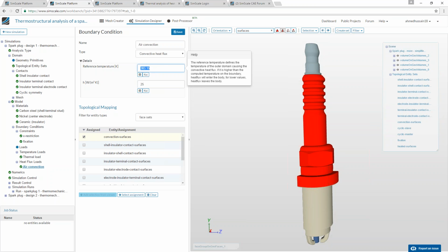Okay, there is another question from Joseph. He said, in the meshing phase, do you have to have a conformal mesh, meaning node-to-node connectivity between nodes across different material blocks? No, you don't have to, if you really have a consistency already, then you probably don't have to.